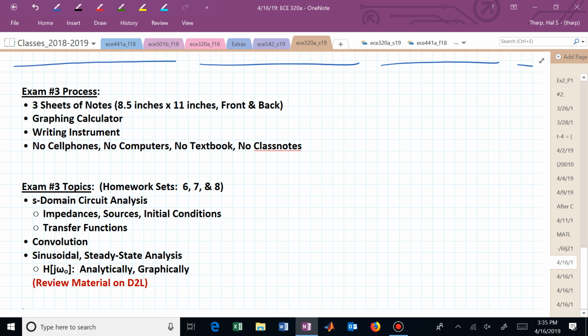You should be able to know when a particular system will see a non-zero output based on when the input is applied and when the impulse response shifts or moves. And can you now find different overlap patterns, or can you now find the value of y, the output, at a particular time? And if you can find when y of t is non-zero, now if I ask you to find y for some time outside of that range, you can immediately say, oh, y of that time is 0. Probably won't do that, but I could.